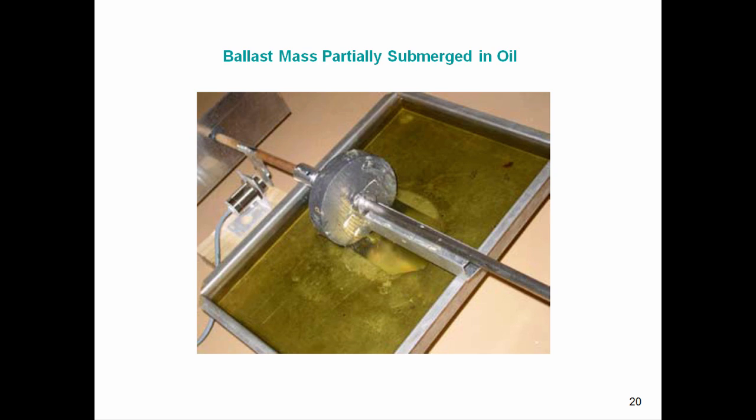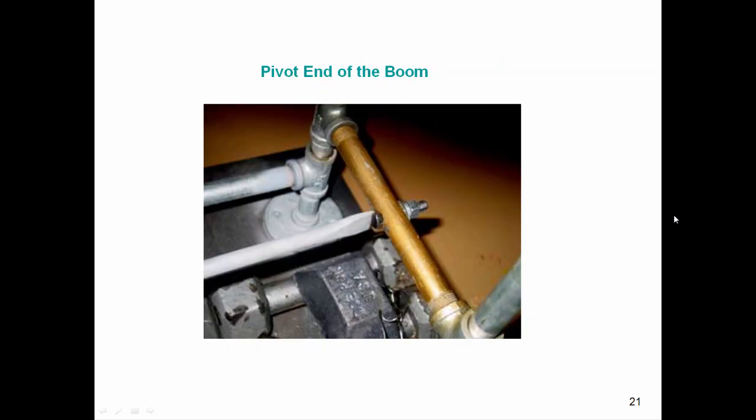And in fact, the classic Lehman seismometer would actually have an electromagnetic coil that would vibrate or oscillate back and forth between the poles of a magnet, and then the resulting current in that coil would be proportional to the velocity of the coil. Well, I tried that and I could not get it to work, but I was able to use this relative displacement sensor and get some good readings. So I was happy. Here is the chisel blade, and it butts up against the chrome polished bolt.